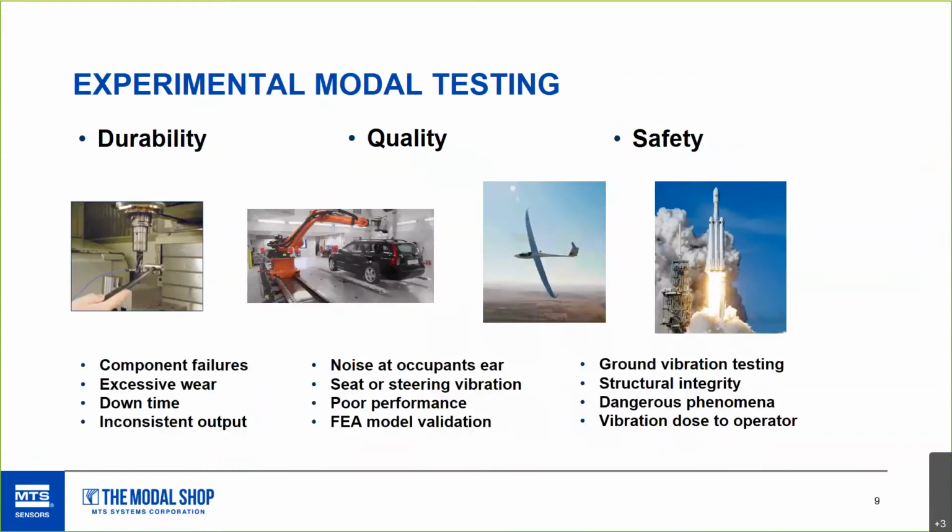But ultimately, why do we care about this modal analysis? Why is this something we're going to do? So again, ideally, we're making all these choices earlier on in your conceptual phase to improve durability, so you don't have, say, excessive wear on a tool or a tool breaking due to some odd vibration at a certain operating speed.